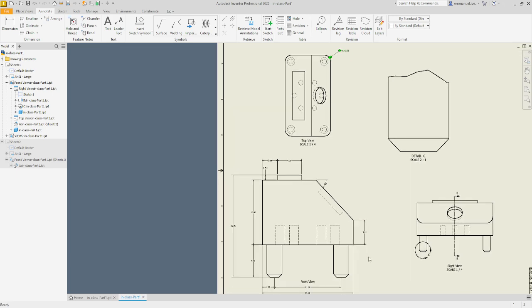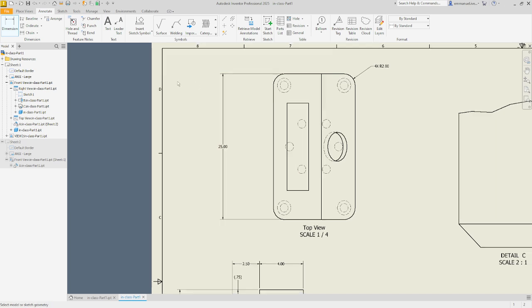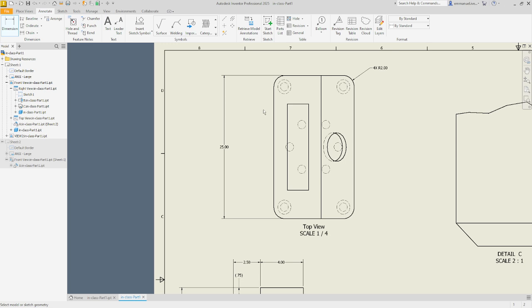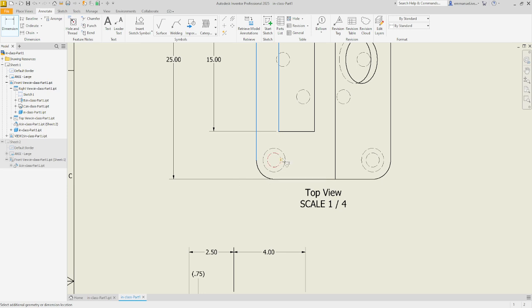Outside of that, I think the only thing I would need is the length from top to bottom here. I would also need the length of this line here. And I already have the 2.5 inches coming from the back edge there, but if I wanted to, I could put in another reference dimension for that, which I won't because I don't feel like crossing over that part like that.